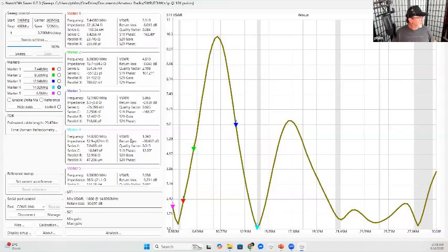Oh yeah, it's most resonant at 14 on 20 meters. It's got a 1.060 VSWR. One thing I don't like, it doesn't remember where all the markers are, so you have to put all the markers out again and play around with it. But I save these setups, then I move my antenna around, and because I'm changing the slope, the angle, the east-west, it does change the VSWR.